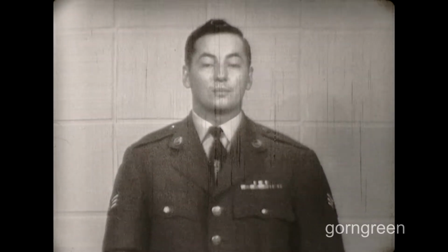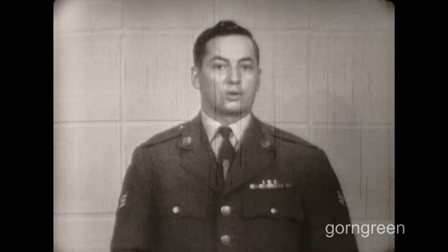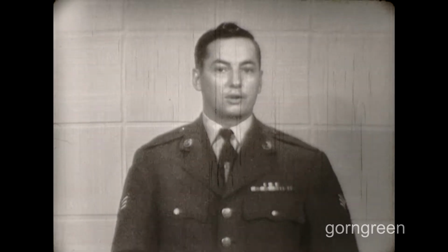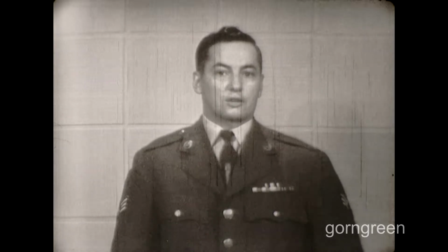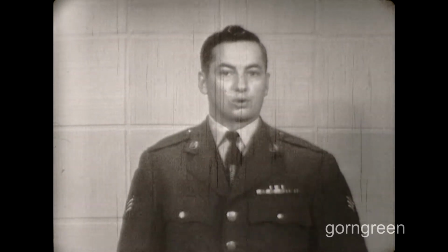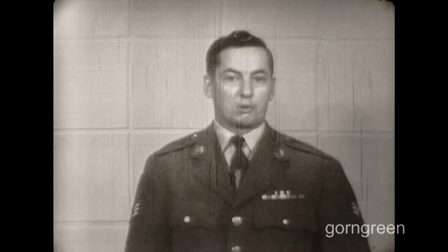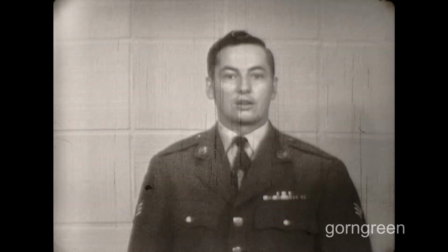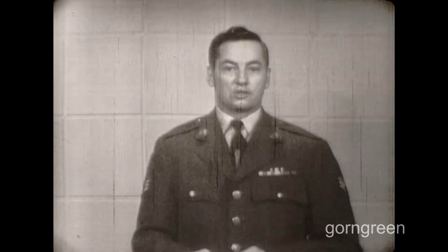What happens to them now? Well, a mathematician named Maxwell derived two very important equations upon which the entire theory of radiation in free space is based. He said that electrostatic lines of force in space produce magnetic lines of force, and magnetic lines of force in space produce electrostatic lines of force. Or in layman's language, the E lines exist because of the H lines, and the H lines exist because of the E lines. As they radiate into free space, they support each other.